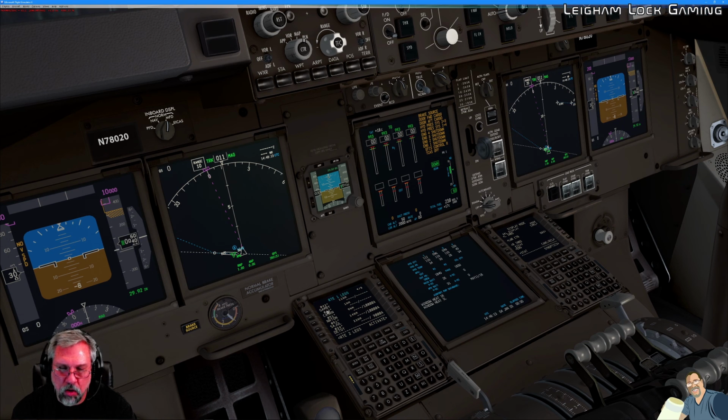Here was our last waypoint from the regular flight plan, and then the procedure for landing on ILS 22 left takes us through some additional waypoints to get lined up and descend down to the runway. So those all look fine. Last few waypoints, and then we have runway 22 left where we'll be landing. You can see we have some altitude constraints as well as a speed constraint as we reach that last waypoint on arrival for JFK.